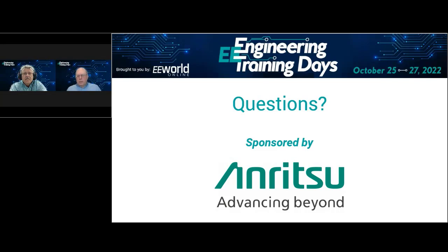I see. You also mentioned that if you apply too much torque to an adapter or to any connector, you can damage it. How do you know if you've applied too much torque? Is there any way to know that? That is an excellent question. I'll talk about a metrology lab environment first. Every connector type has a specified torque rating, and there are torque wrenches made specifically to address that. I'll take a K type, which is an Anritsu 2.92 millimeter connector. I believe it's 8 inch-pounds is the torque rating. So you can buy a torque wrench that will only allow you to torque that connector to 8 inch-pounds and not more than that.